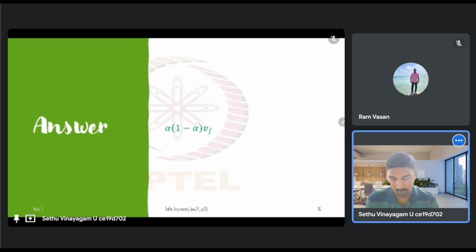Okay. So to find the speed of the shock wave separating traffic states A and B, we know it is QA minus QB, right? Over Ka minus Kb, right? So that's all. So we need to know these four numbers QA, QB, Ka, Kb. Then we can find the speed. So here, what are the two traffic states?